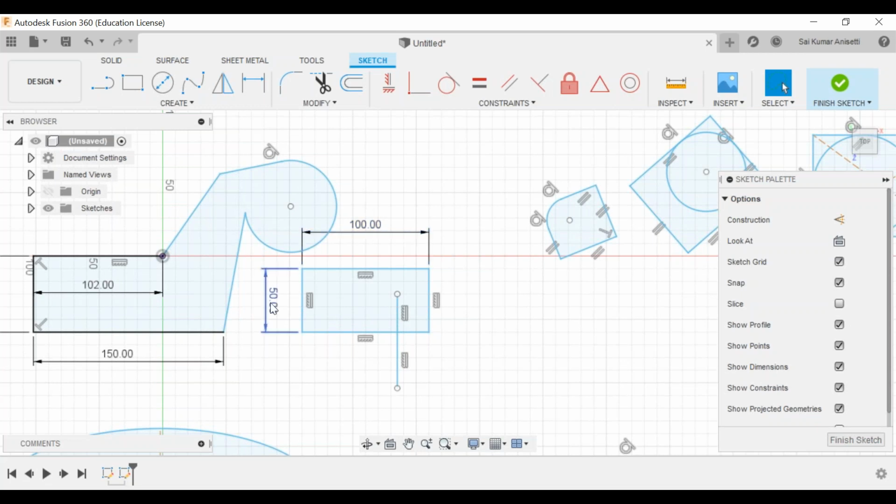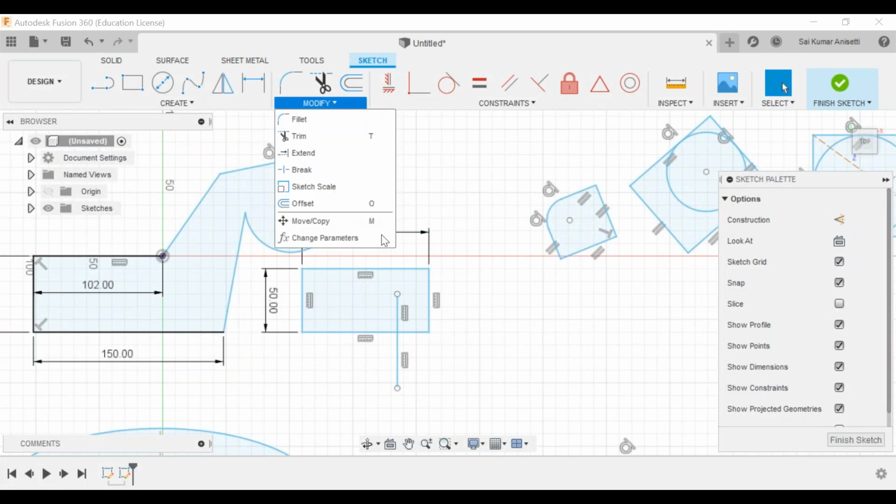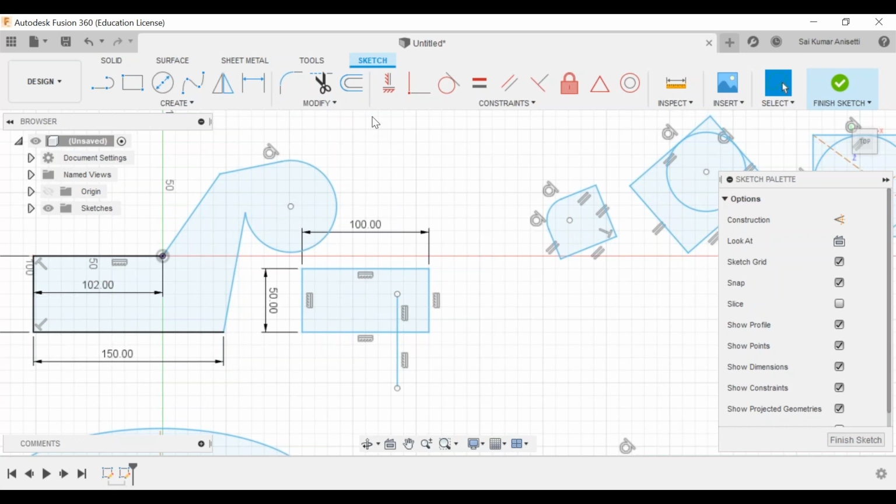Now I'll give a formula as d7 is equal to twice the times of d6, and then it automatically takes the value, or else d6 by 2. So in the form of parametric modeling, I'll give this dimension. That is how parametric modeling works. It takes a complete class to define your formulas and all. So that is the major advanced course in the Sketcher workbench, about changing parameters, giving formulas and all. I'll take a complete class on parametric modeling later on.